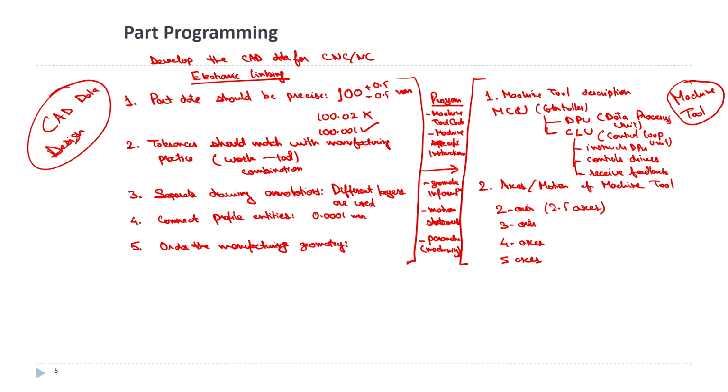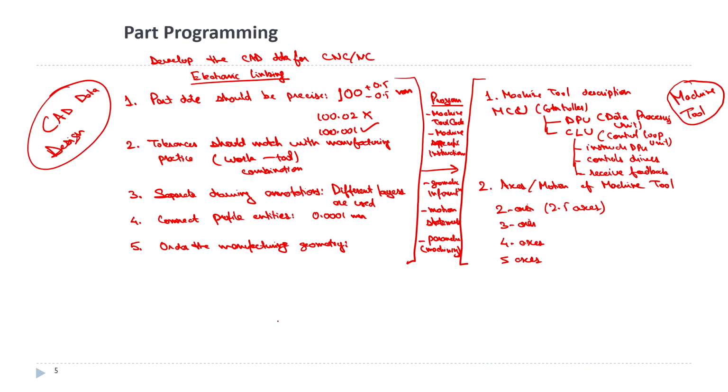So, in NC machine tools, each axis motion is equipped with a driving device to replace the hand wheel of a conventional machine, because in a conventional machine, suppose drilling is to be done, it is a hand wheel that helps us do the drilling. In NC machines, it is a drive, a motor drive or some mechanical or hydraulic drive that drives your drill down to do the drilling. So, a driving device may be a DC motor. Axis of motion is defined as an axis where relative motion between the cutting tool and workpiece occurs.